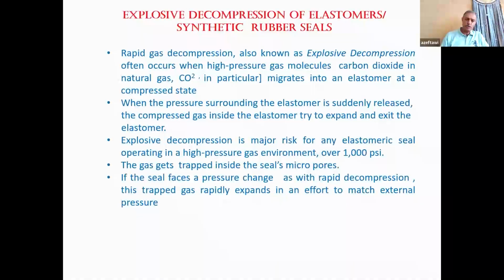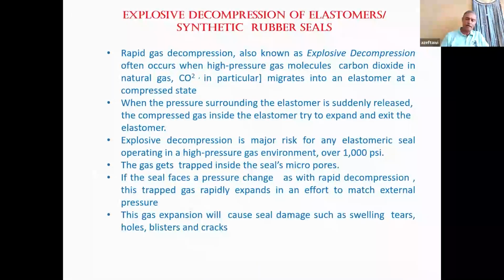The explosive decomposition, this is a phenomenon that happens to all rubber items you have in your rig, especially in your pressure control equipment, where this rubber absorbs gases. So it keeps absorbing gases till full saturation. When it is hot, when temperature is raised, gas would like to expand, but it cannot expand because this is a confined space. So what the gas does, it creates blistering, tearing, cracking to this rubber element.